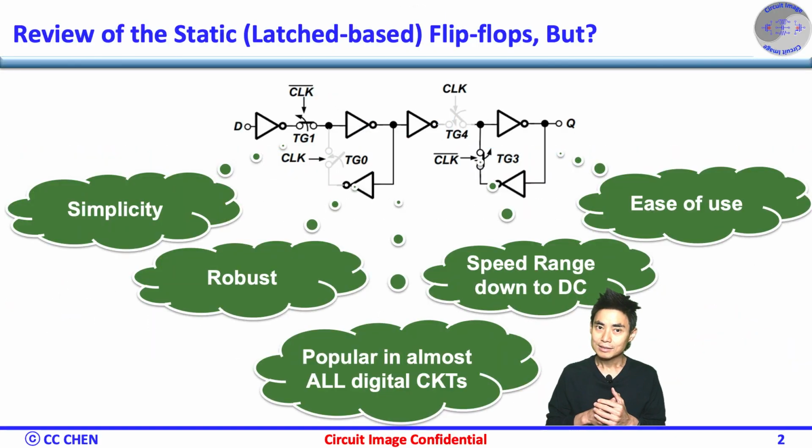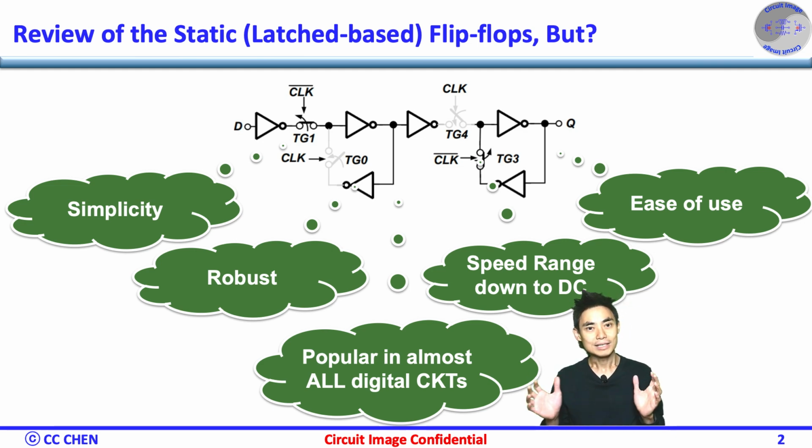Before understanding the dynamic flops, let's review the static latch-based flip-flops, which are commonly used in a digital system for several reasons as follows. First, the transmission gate stack flop is simple and easy to use. Second, the static flops are reliable for storing and transferring data. Without input changes, the output may stay constant forever. Third, the static flop can operate in high-speed applications.